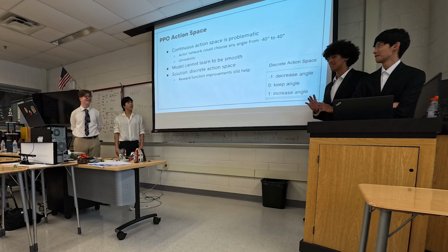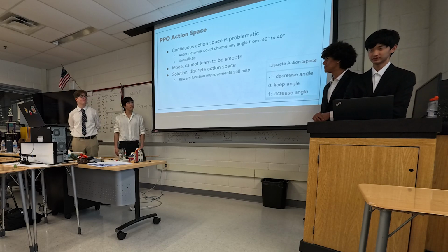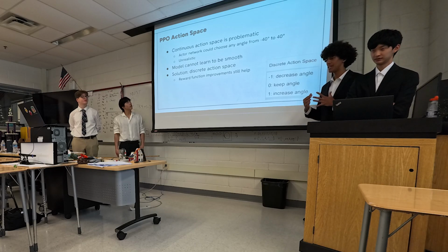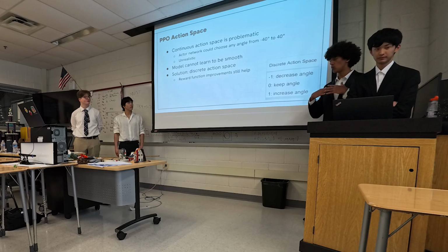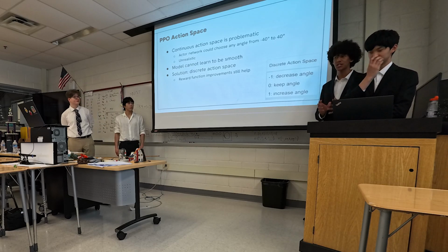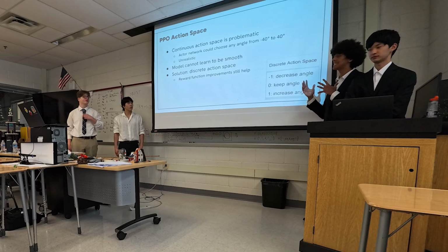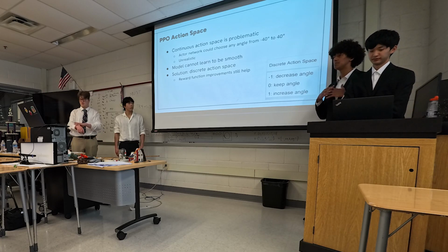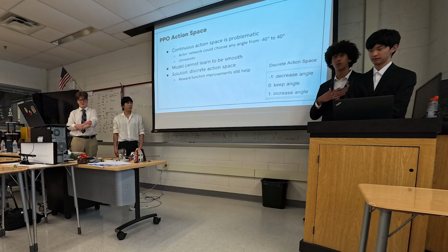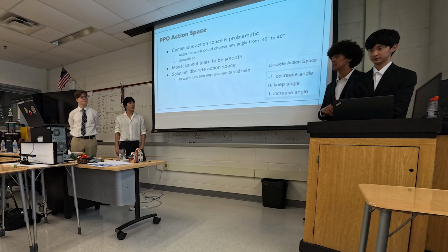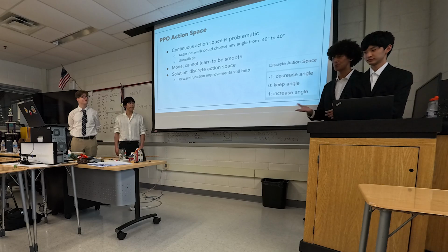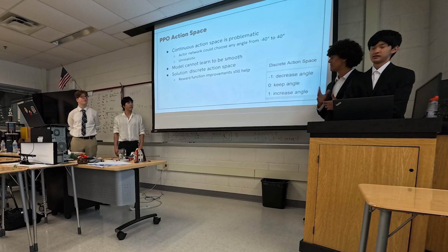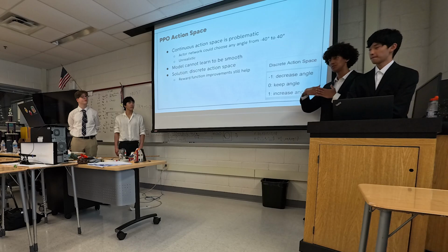No matter what we tried on our simulated ball and beam environment, we couldn't get the model to properly balance the ball in a way that we felt was realistic for implementing on a physical model. The main issue we saw was that since we were giving the agent a continuous action space to sample from, meaning it could take an angle at any given time step, the agent could pick an angle anywhere between -40 degrees and 40 degrees to set the beam angle to. What the model would do in our simulation was teleport between very large and very small angles, which isn't realistic for a physical model because teleportation does not exist. So the main issue is that our model could not learn to have a smooth transition between beam angles.